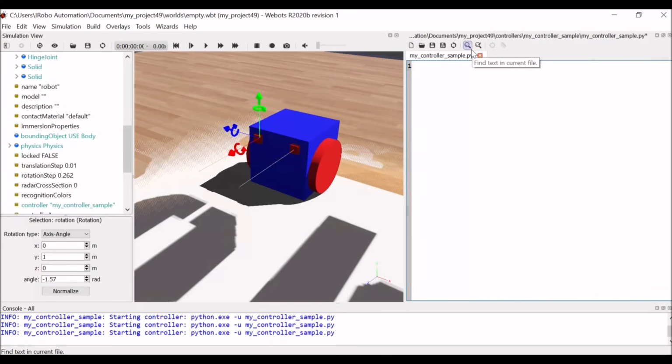As usual, we should call the robot library to the controller, that is, from controller import Robot. Next there is a time step that is equal to 64, an integer value, that means 64 milliseconds, and threshold, that is the sensor threshold, is 850. Actually the maximum value is 1000. Okay.